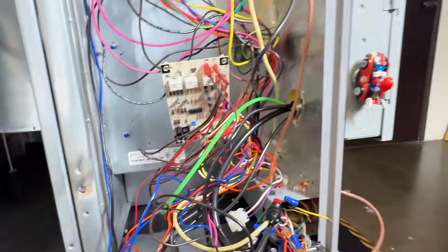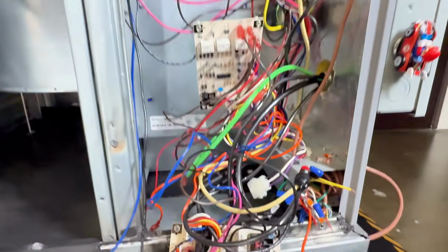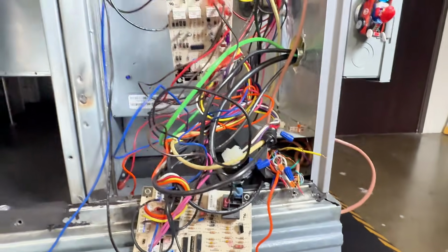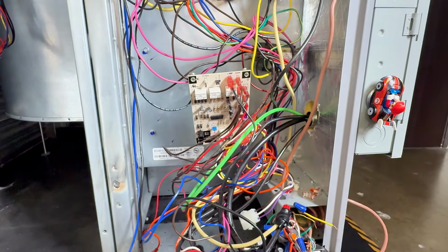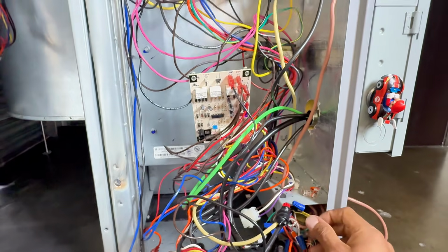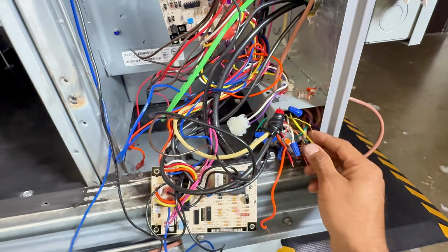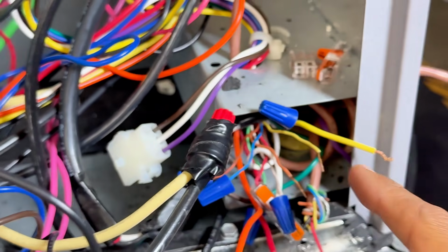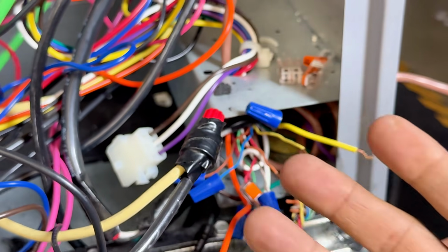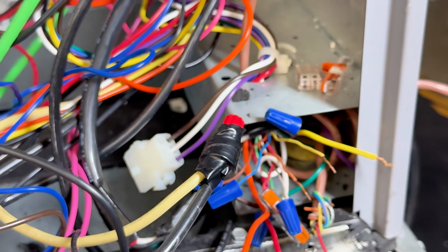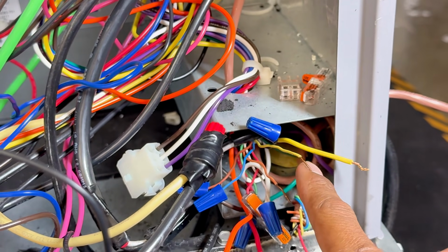All right, Mario. Mario takes a little bit of a, he has to go through a couple more bridges. Couple more bridges. So when I have a call for cooling, okay, so let's go here. When I have a call for cooling, we're sending 24 volts, right? To activate the compressor, right, for the contactor coil. Okay, so let's start right here.